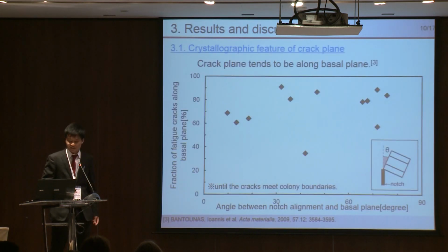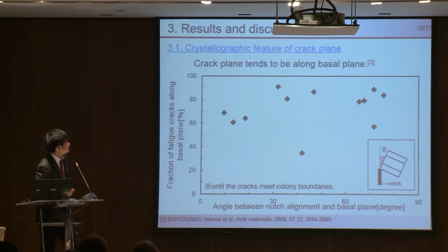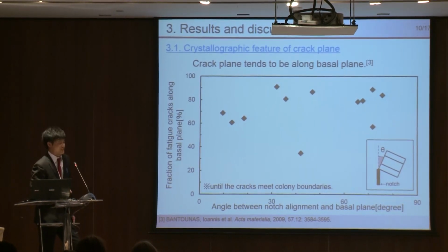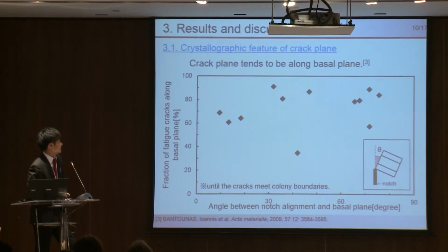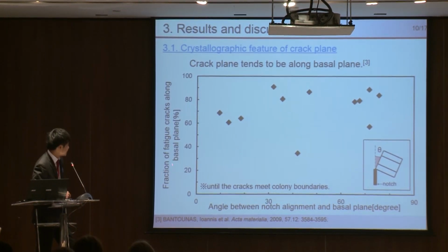Next is results and discussion. First, I introduce the crystallographic feature of the crack plane. It was reported that crack planes tend to be along the basal plane. So we calculated the fraction of fatigue cracks along the basal plane.